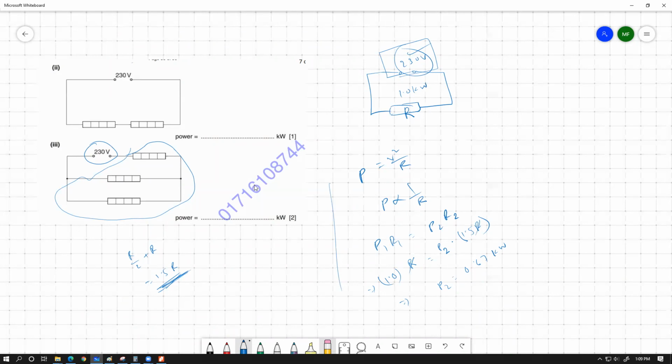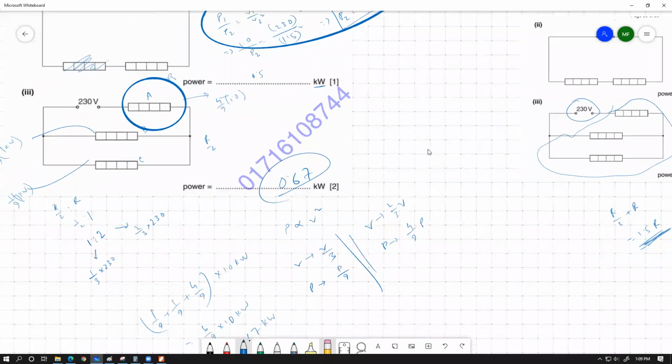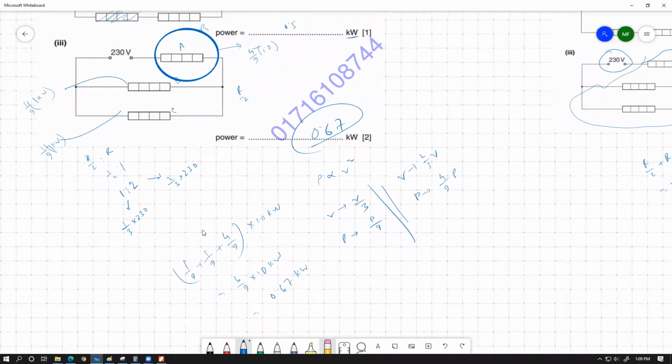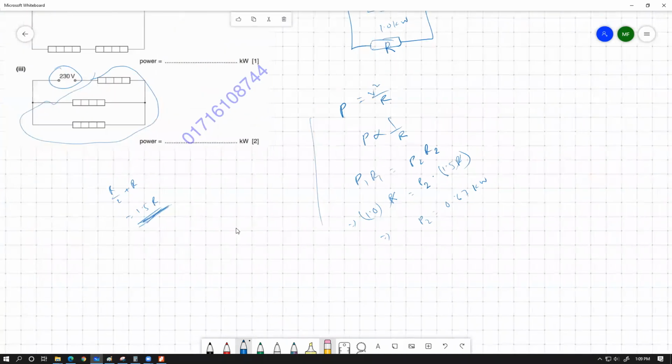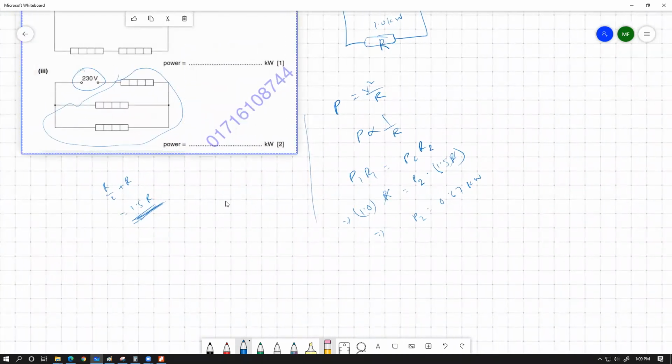It can be difficult if you don't understand what to take constant and how to approach the circuit. In this case, I considered the supply to be constant and the resistance to be the variable. Whereas in the other calculation, I went through the whole process: I calculated the individual power of the heating elements, 1/9, 1/9, and 4/9, depending on how the available voltage changed. Then I summed those and calculated the total power of the whole system. So that is a much more dissected version of the calculation, whereas this one is a far more simplified version of the same calculation.